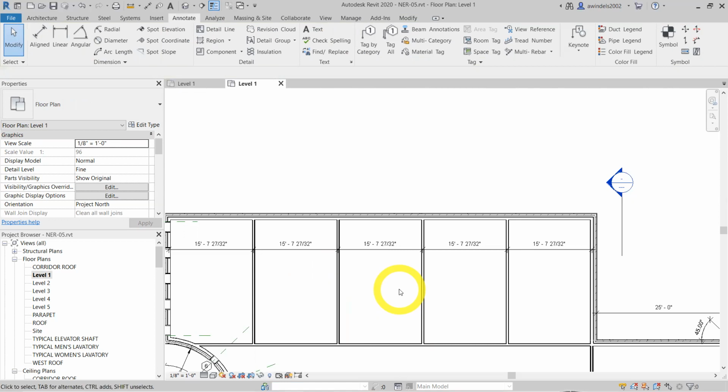So this next part is about constraining a model, which dimensions do part of that, which we just did. You can definitely over constrain a model with too many things, so nothing can be moved. You can under constrain it, so too many things don't move with each other in ways you want. So you can definitely go one of both ways, is what it's kind of trying to say. So it's going to show you what you try to do to unconstrain something we just did here, for example.